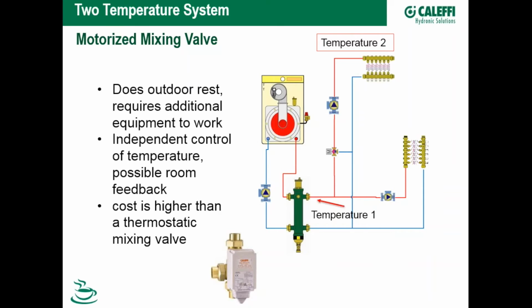Typically, when I look at motorized mixing valves, I'm probably going to start thinking about it if the area I'm trying to control is more than about 1,000 square feet. Then I can start thinking about the budget and probably justify the higher upfront cost of the motorized mixing valve.